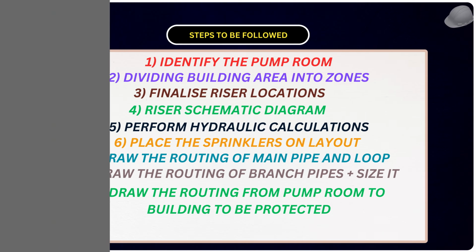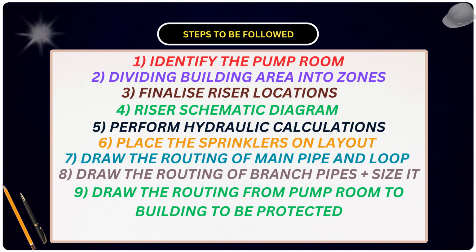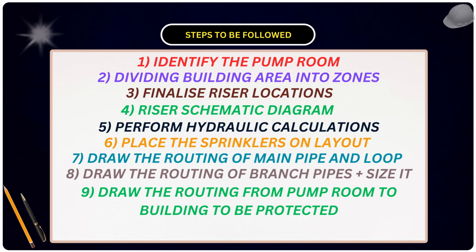Steps to be followed. Number 1. Identify the pump room location. Number 2. Divide the building area into zones. Number 3. Finalize the riser locations. Number 4. Prepare riser schematic diagram. Number 5. Perform hydraulic calculations.